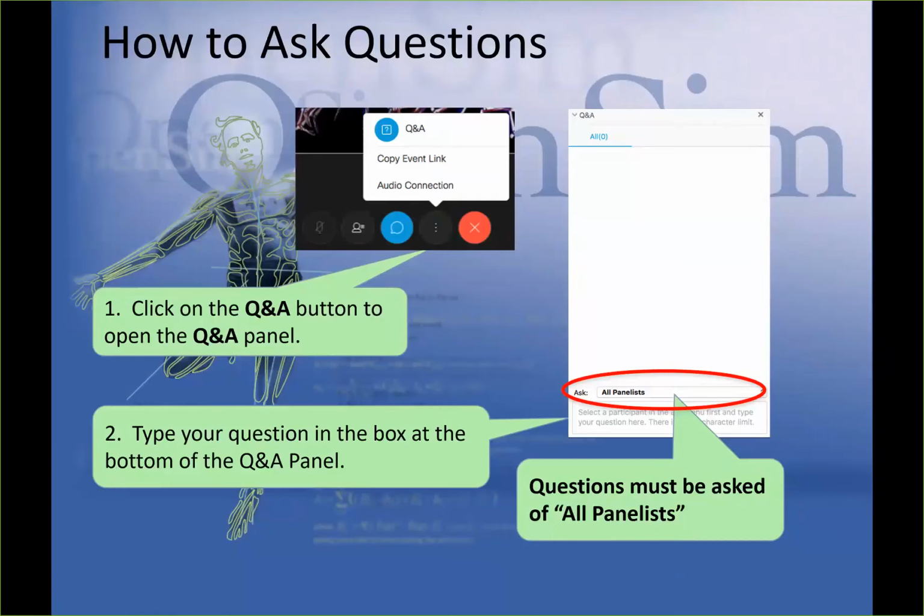Well, it depends on what you mean by that. If you're trying to see how different muscle activation changes the curvature of the spine without changing the rotation of the head, that'd be a little more difficult. It might be possible with the decoupled kinematic constraints that are in Calvin's model. But if instead you're just meaning predicting muscle forces based on different postures or different inputs to the head, yes, that is very simple to do using computed muscle control or static optimization.